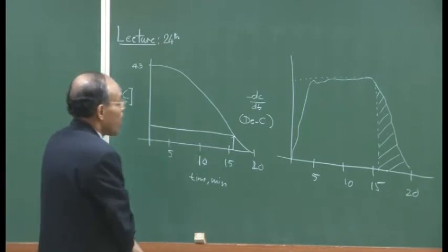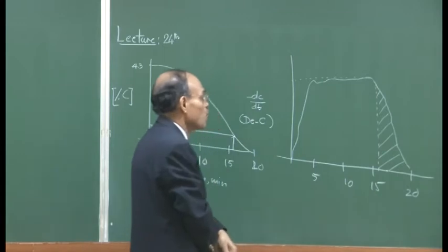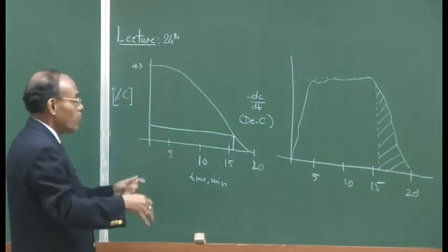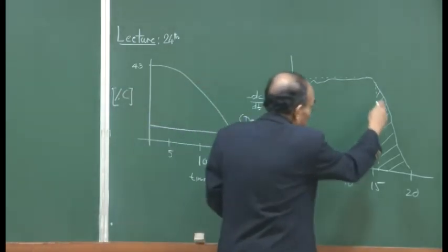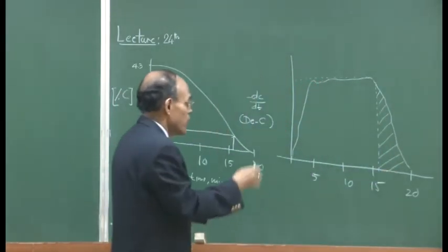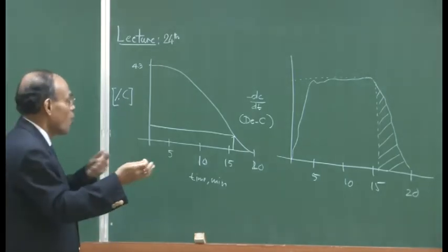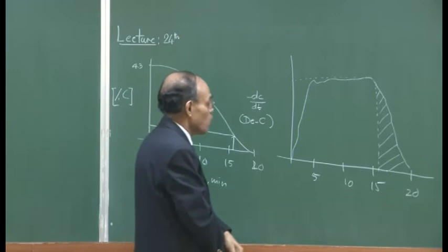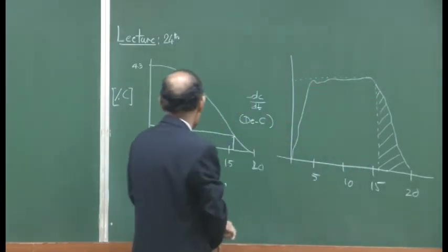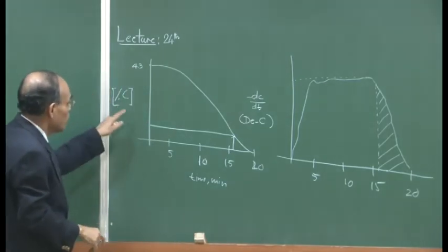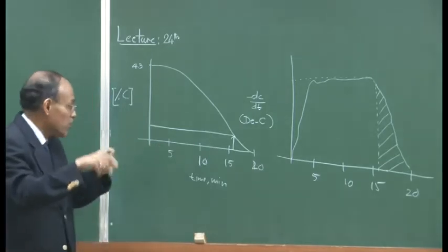Once we have the end of the steady state decarburization period known to us, which is the characteristic of a particular converter in a particular steel plant, this part will depend mostly on how you are changing the blowing pattern, whether you continue to blow the same oxygen or less oxygen, and so on and so forth. So, the end of the decarburization period in the bath will be more or less the same in a particular converter in a particular steel plant.